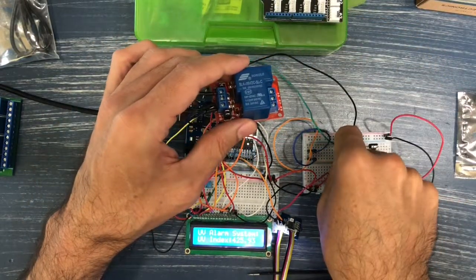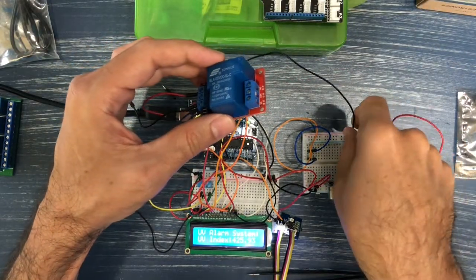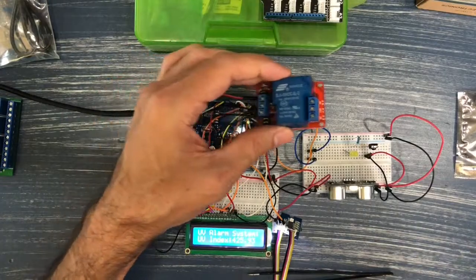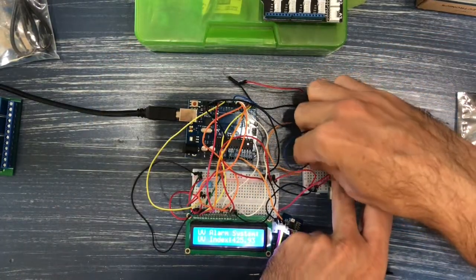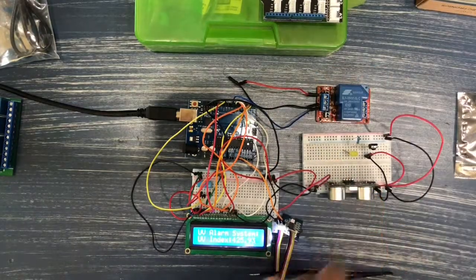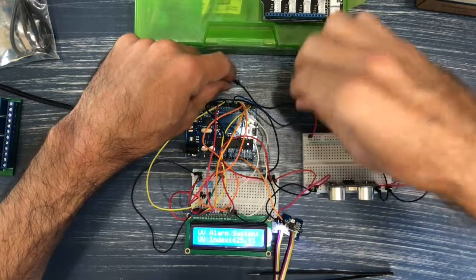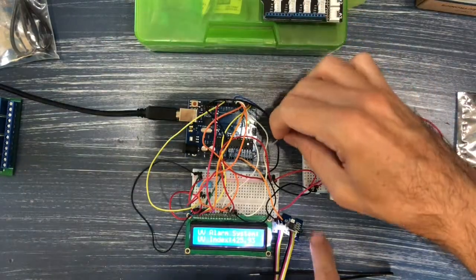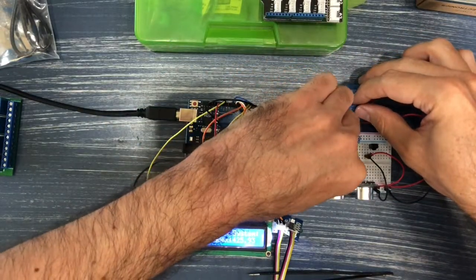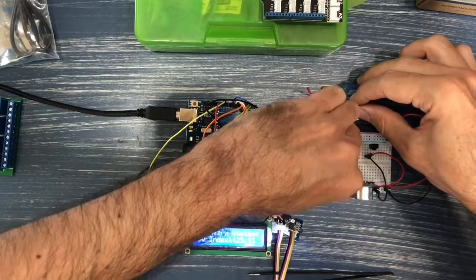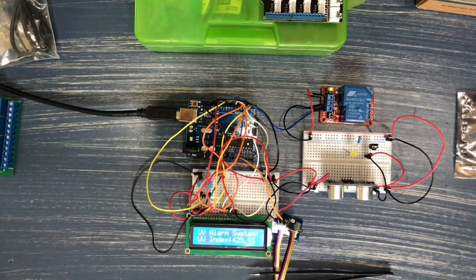We are not actually going to be connecting the high side to anything, but you can connect the high side pretty much to a whole host of common stuff like desk lamps. I've got one controlling a compressor. You can hook it up to motors. It's very common. Solenoid valves and stuff like that. So in this case, we're just going to see how the relay works, and in future videos we're going to look at how we can actually use them in more powerful circuits.